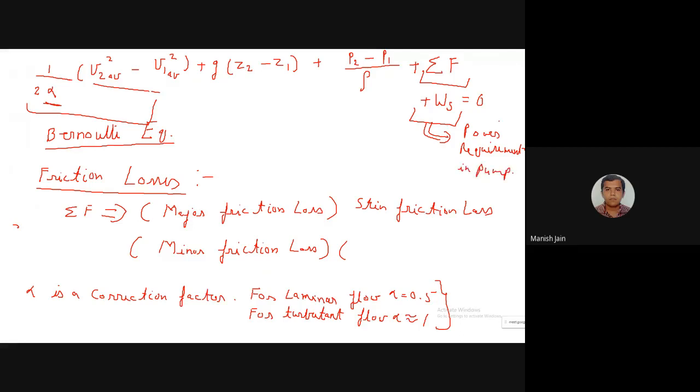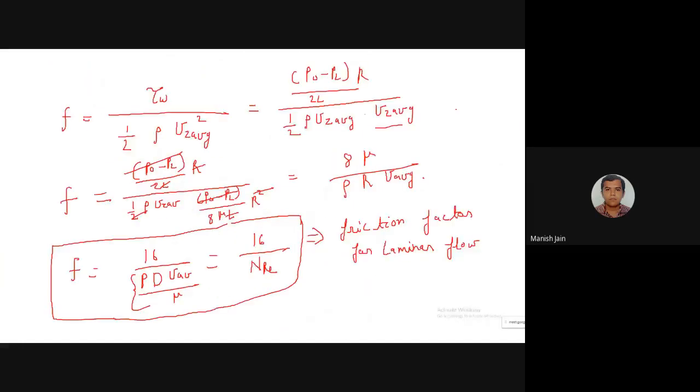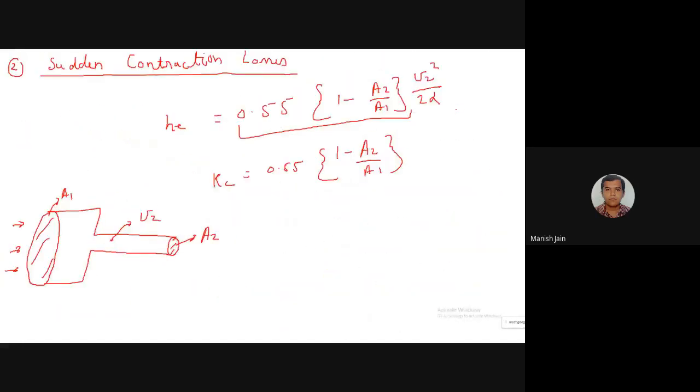Again, when you calculate the power requirement from the Bernoulli equation, this equation shows you the theoretical power requirement. Actually, the pump has its efficiency. The efficiency of pumps is generally 0.8, 80%. So it converts 80% of the electrical energy into mechanical energy. So if your power requirement is 2 horsepower, you have to divide 2 horsepower by 0.8, and you will get the actual size of the pump. In this way you can calculate what should be the size of the pump. We will solve the problems related to this derivation in the next few classes.